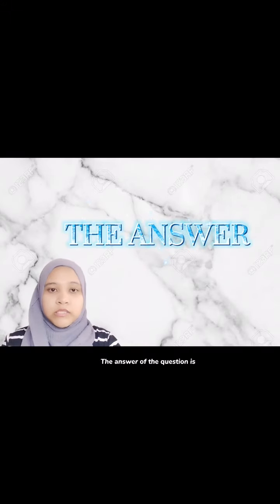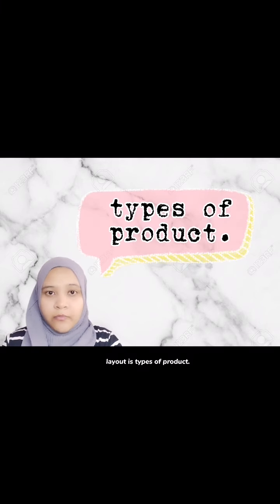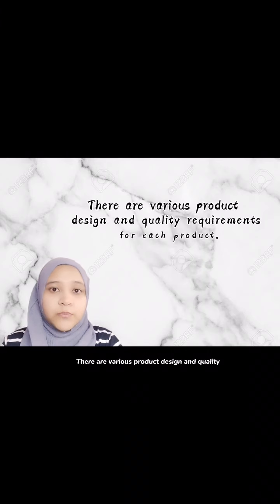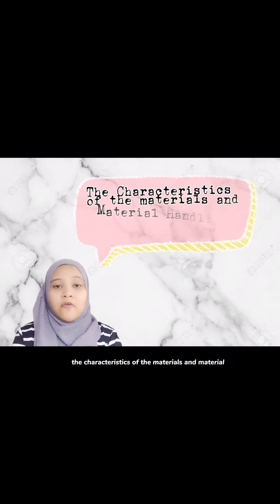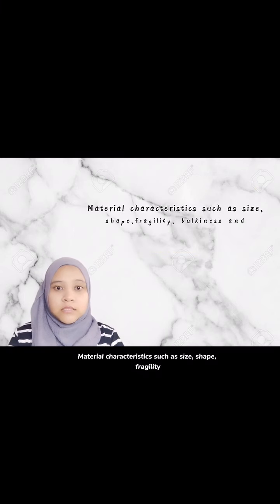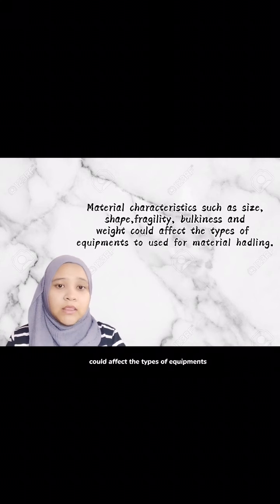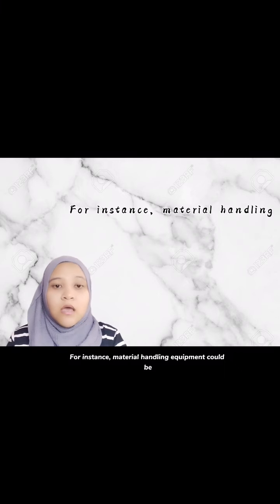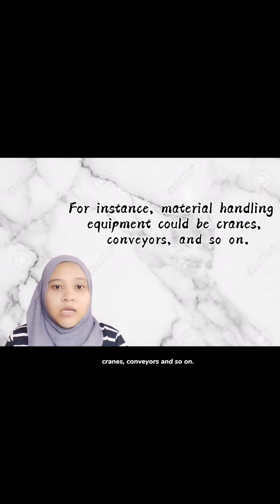The answer to the question is, the first determinant in designing a facility layout is the type of product. The product can be categorized as goods or service. There are various product design and quality requirements for each product. Next, the characteristics of the materials and material handling equipment. Material characteristics such as size, shape, fragility, bulkiness, and weight could affect the types of equipment to use for material handling. For instance, material handling equipment could be cranes, conveyors, and so on.